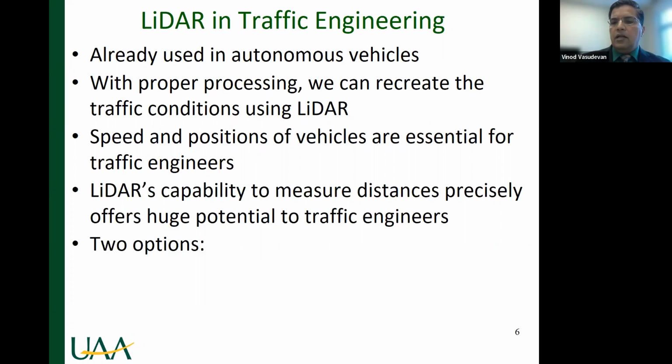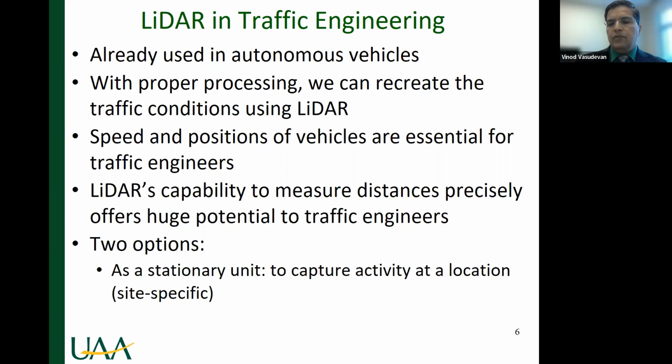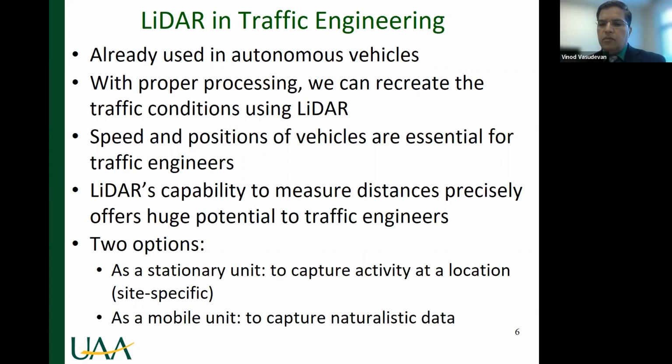Now, to collect these data to measure these distances, there are two options. One is to go with a stationary unit. You are using a static kind of LiDAR unit, and then just like a video camera, it would be very site specific, where you are capturing the information of a particular region. It can be an intersection, it can be a mid-block, etc. Another option is to use it as a mobile unit. That's what I'll be focusing on in today's presentation.